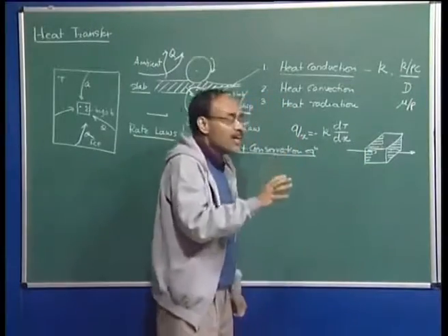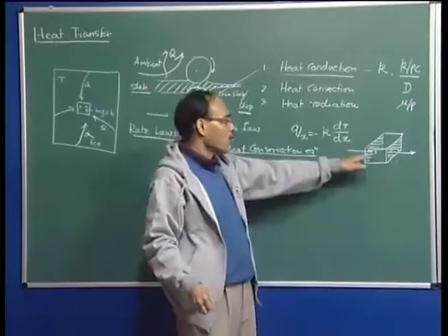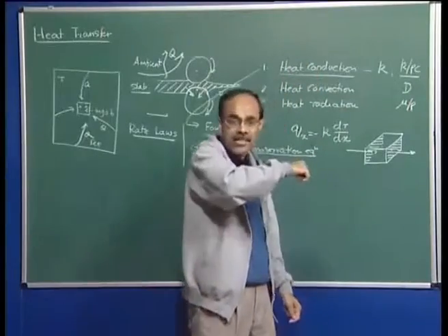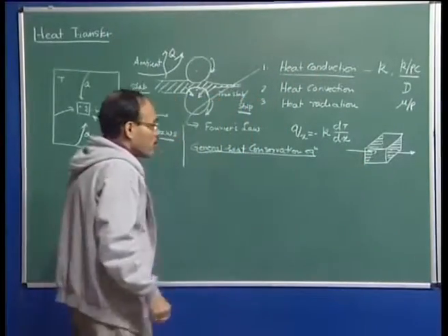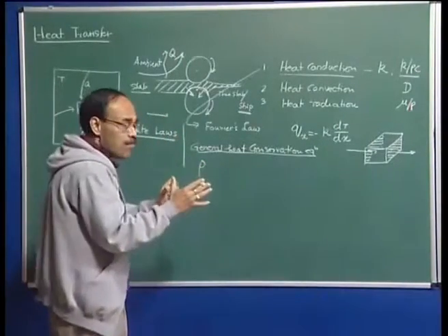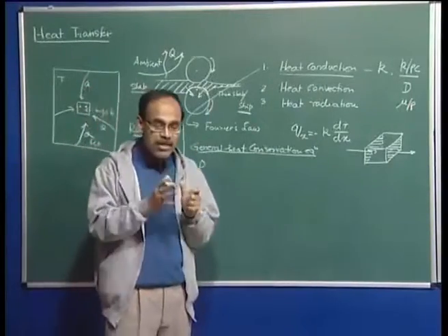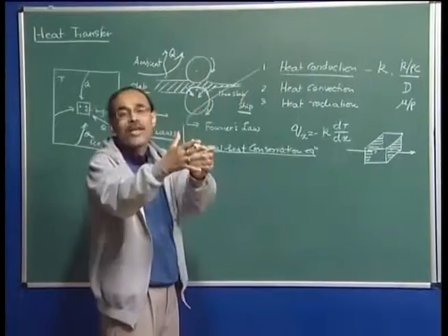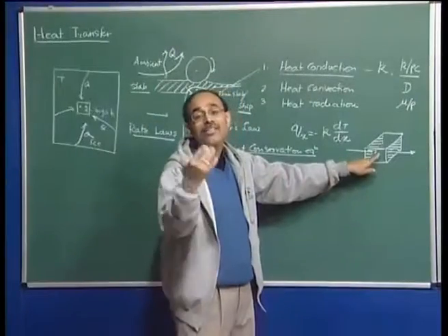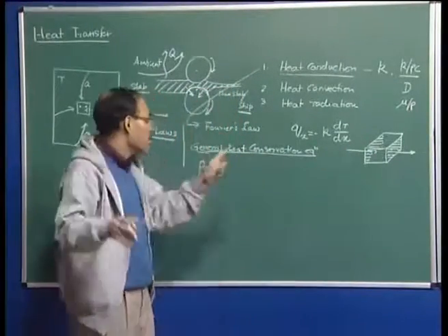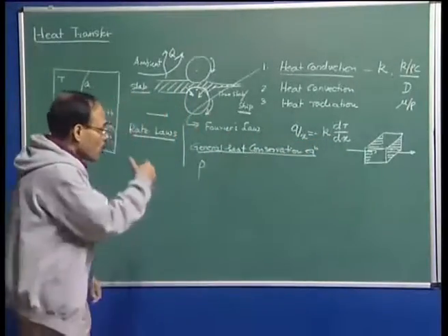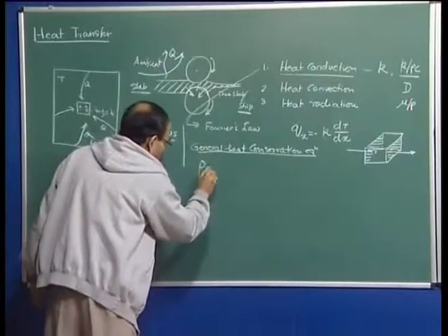So therefore we can say that the net rate of change of temperature of the body is going to be determined by the heat coming in and heat going out in 3 different space directions, as well as the rate of heat generation. And therefore if you write this equation, it means that you have heat coming in minus heat going out in all 3 directions, plus or minus heat generated in the system, is equal to net rate of heat accumulation. This is the energy conservation statement in words, and if I use Fourier's law to convert this statement into mathematical form, this is what we have seen.